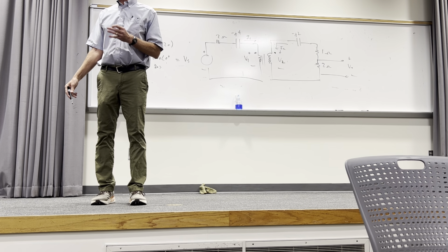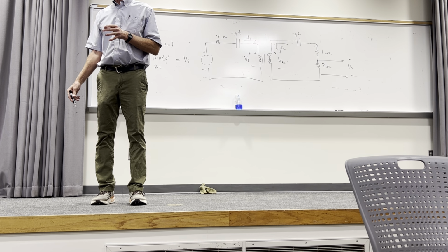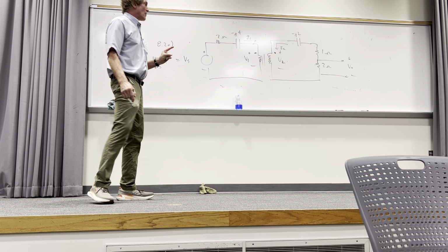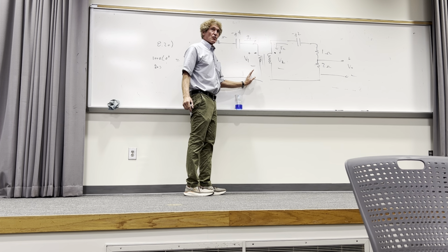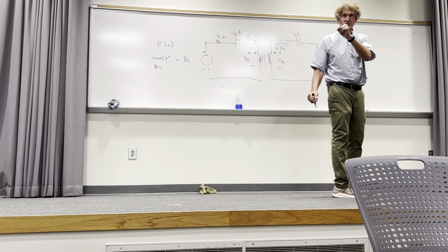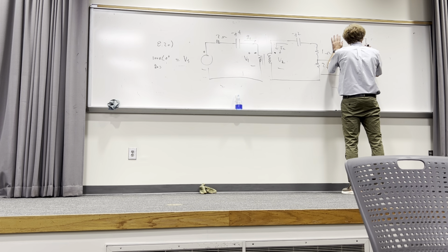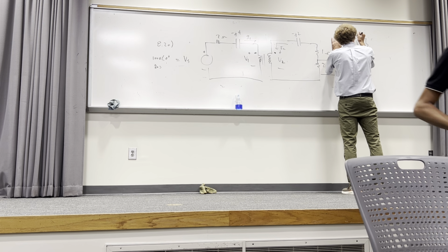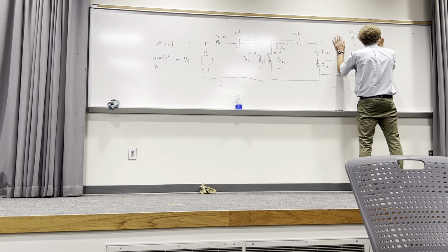Every step that I'm going to show you in this problem is important to understand. Can everybody follow me? Here's the first thing that you do. You have to find out what the impedance would be across this transformer looking through the primary side. That's the first step, and it is the critical step. So when I look at this transformer, I want to know what the equivalent Zn is here. That's what I'm looking for. I have this on the other side.